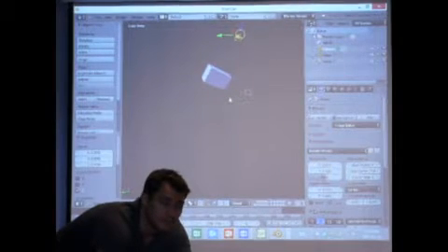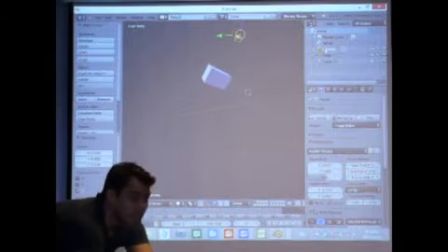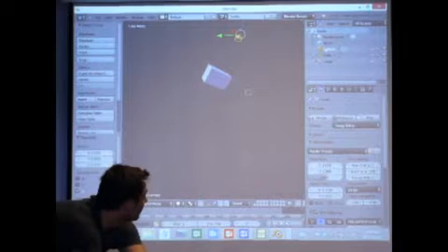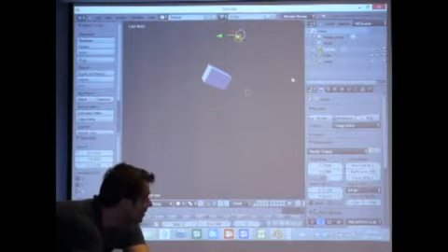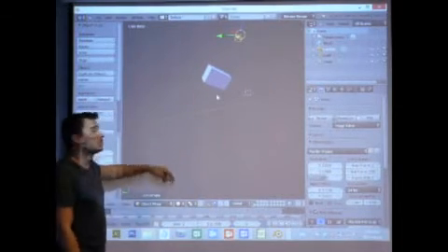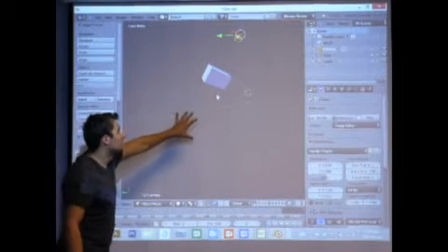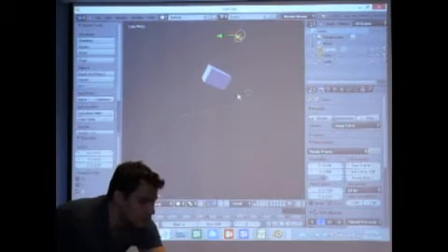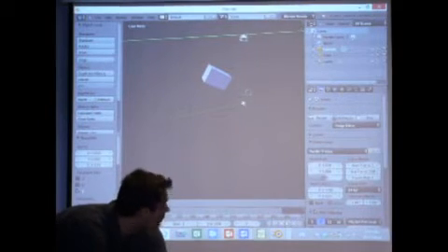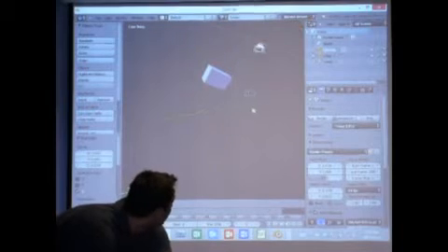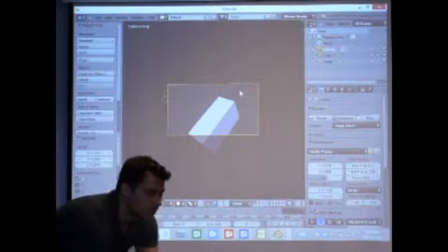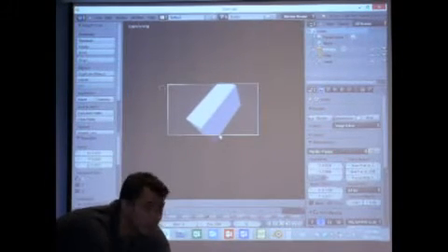Could you say it again? So if you select the camera on the top right, it'll show up in white with an orange outline, which just means it's selected. You have to make sure your mouse is actually inside this window. That's very important. If your mouse is over here, it's not going to work. Make sure it's inside, then press G. Just by pressing G, you can move the camera around. G for translate. You can pick the different dimensions, X, Y, or Z, depending on where you want to move it. And if you use numpad 0, you can take a look at what the camera is looking at as you're moving your camera.